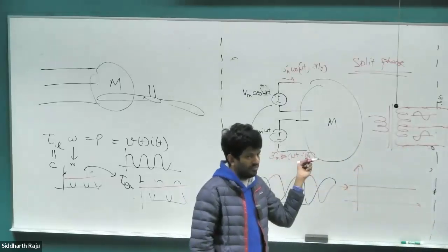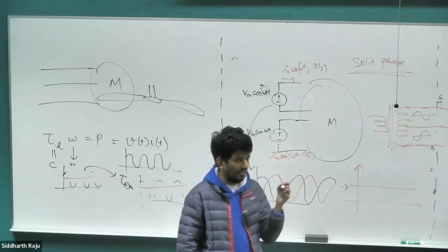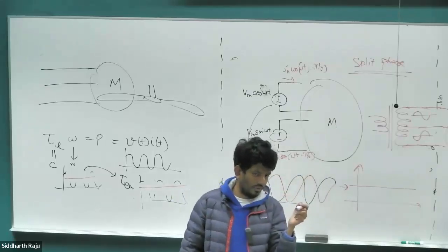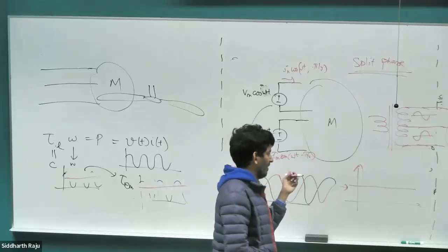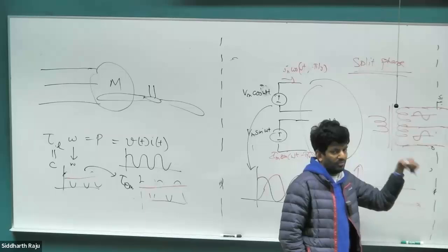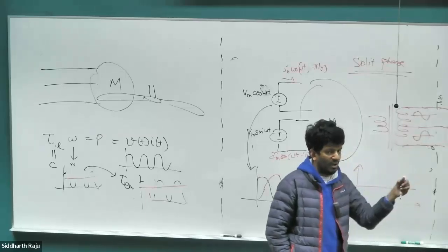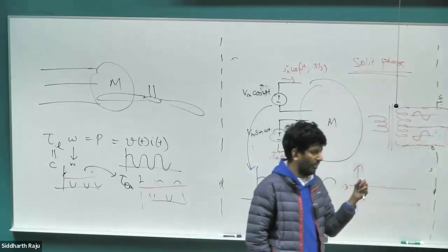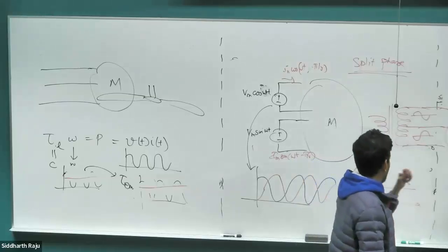Because it requires quite a lot of power. If you give 120 volts, the current is going to be too large. And if the current is too large, that's going to make the motor a little bit more complicated to design and much bigger in size. So you want to limit the current. That way you use a larger voltage. If you double your voltage, your current can be half for the same amount of power. Right? So your motor can be a little bit smaller and more compact.